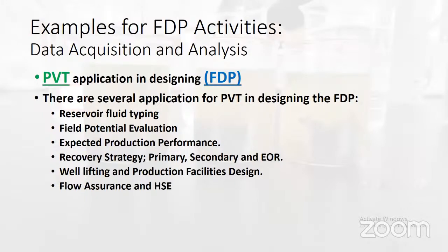But for very heavy oil, we can recommend that we don't need any separator. You can go directly to the stock tank, because we don't have a very high GOR. But in the case of a volatile oil reservoir, we may lose a lot of oil into the gas phase if we don't have multi-stage separation in our facilities.